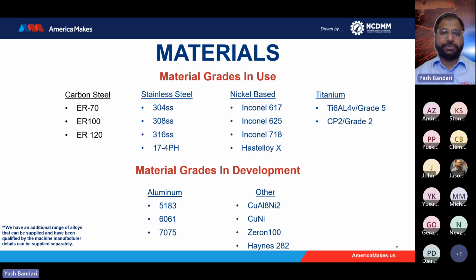In addition to stainless, nickel-based alloys, and titaniums, we have qualified a lot of materials. Qualification as in not just printing a block and taking a couple of samples, but evaluating everything right from hardness to all the mechanical properties involved to microstructure. So this is an ongoing project.